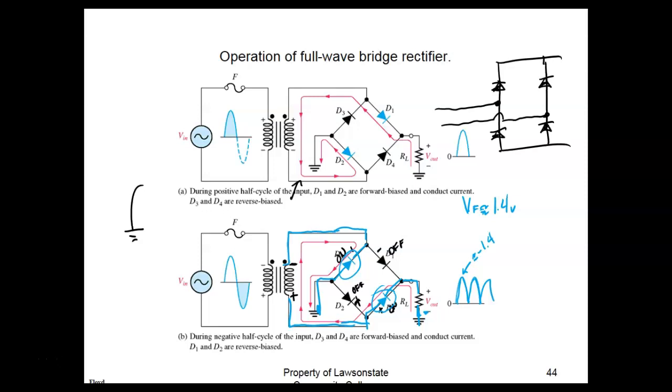We got some battery chargers, by the way, that were used to charge golf carts, and they use a center tap transformer. So they use a full wave center tap. It uses 2 big diodes, and then they have the 2 diodes. This is where one of the diodes actually went out. It wasn't my battery charger; it was on that golf cart charger. One of the diodes went out, and it was actually spot welded to the chassis. So I had to grind it off and make a hole and put another mount diode in there.